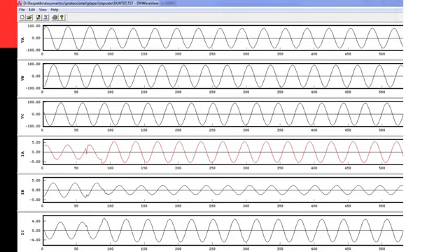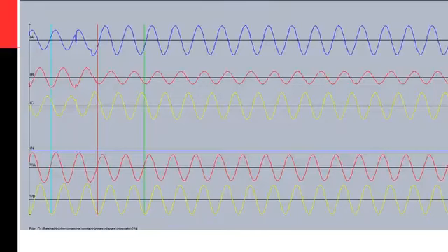If you see, we are talking about the same oscillography represented using different tools. Since COMTRADE is a standard, all the oscillographies are represented the same in all the different tools. Here I'm using GE's UR EnerVista configuration tool. They have a very good COMTRADE tool. Here I'm using one from another relay manufacturer.